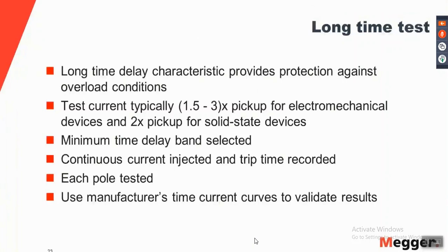The long time delay characteristic provides protection against overload conditions. This is a case where the current may increase, but it may not go up to a level seen in short circuit conditions. The current can result in eventual heating up of the breaker. So in this case, typically there will be a delay of a few seconds, but eventually the breaker will need to trip.